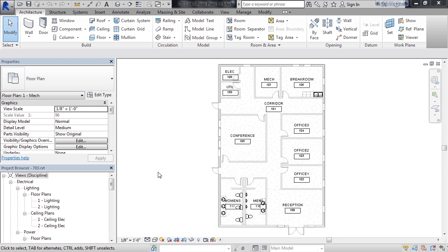Well, it has to do with zones, or think of heating and cooling within a building. You have different thermostats in different places in an office, and that thermostat controls a zone, which could consist of multiple spaces. But let's say one of your spaces crosses between zones. You can't have that, so we need to actually separate that space or make a separation line so that space can now be in one zone and the other part of it in the other zone.